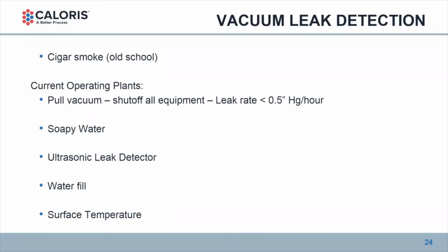Occasionally, we do need to go to the option of water filling, which is why, when we're designing a new evaporator system, the catastrophic weight requirement for the foundation is always a water-filled scenario. We may not necessarily be able to fill it all the way. On an MVR evaporator, we can only fill as high as the vapor ducting will allow.